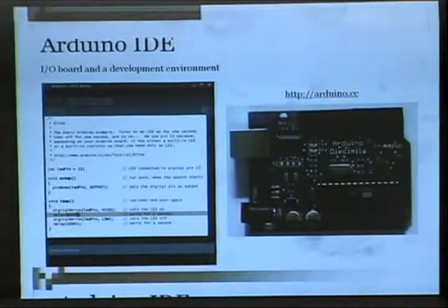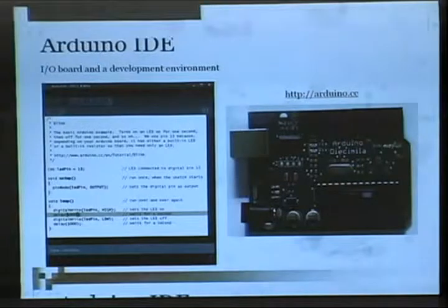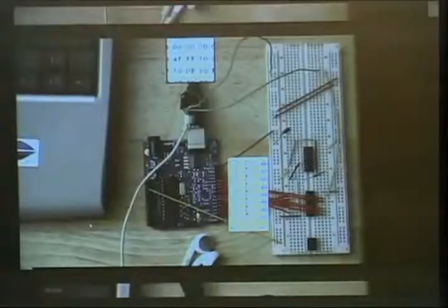How do I do this? Well, there's this tool called Arduino which let me do that very easily. Its IDE is very easy to use. It lets me control this microcontroller, which lets me set these pins, digital pins on the top, to on or off very easily. Like you can see in the code, digital write pin, set pin 6 to 1.